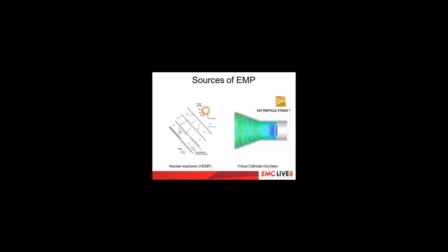However, the electrons are still attracted by the anode and repulsed by each other, so they change direction and fly back towards the anode, only to pass through again and be repulsed by the cathode and attracted towards the anode. So these rapidly accelerating and decelerating electrons oscillating back and forth between the real and virtual cathode through the mesh anode produce electromagnetic radiation at microwave frequencies. And CST's Particle Studio product is an ideal tool for analyzing such devices.